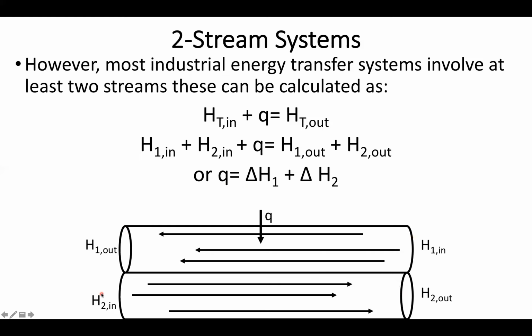condense to the heat being equal to the change in enthalpy of the first stream and the change in enthalpy of the second stream. Now, because of these kind of notations, and the fact that I never know the starting enthalpy of any given species, we're often going to want to set a basis that's going to be the most convenient for you. So the one that you're going to most commonly see me using is that the starting enthalpy of my inputs are generally going to be 0, and I'm going to be looking at how much they're increasing or decreasing along the way. So putting more of the focus away from this input-output notation to this change in enthalpy, encapsulating these two features together.